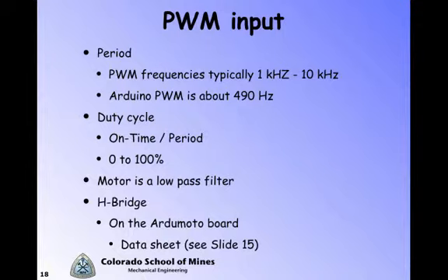At the rate of one cycle every 2 milliseconds, around 500 hertz, that field just can't respond at that rate. As a result, the motor just keeps turning. And that's good because that allows us to do speed control with this much simpler interface.